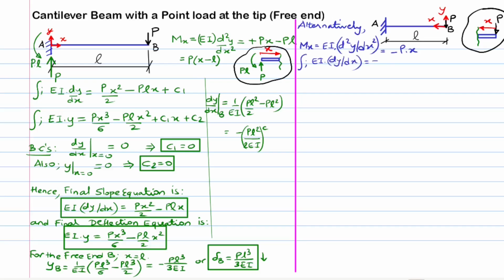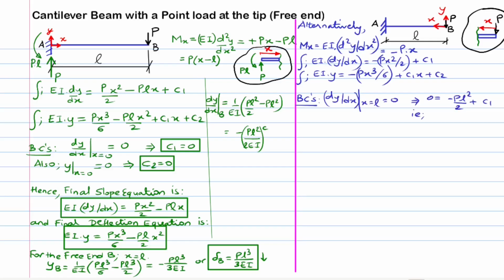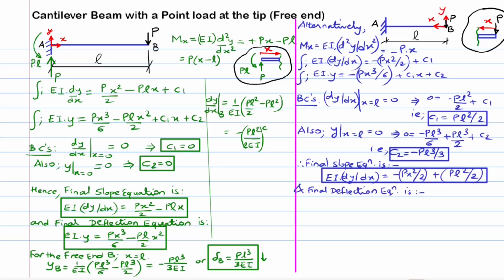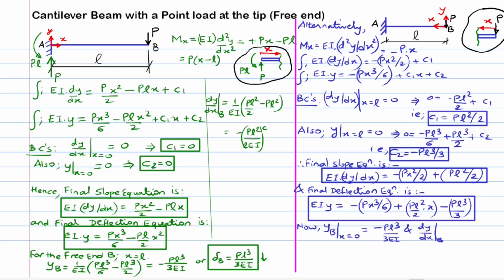You may note that the same result may be reached by reducing our calculations if we assumed the reference coordinate to be located at the free end of the cantilever beam instead of at the fixed support. Also note that though the slope values at the free end obtained by both the methods are the same, the sign differs. This is due to the fact that the reference coordinate system has been shifted in position and orientation.